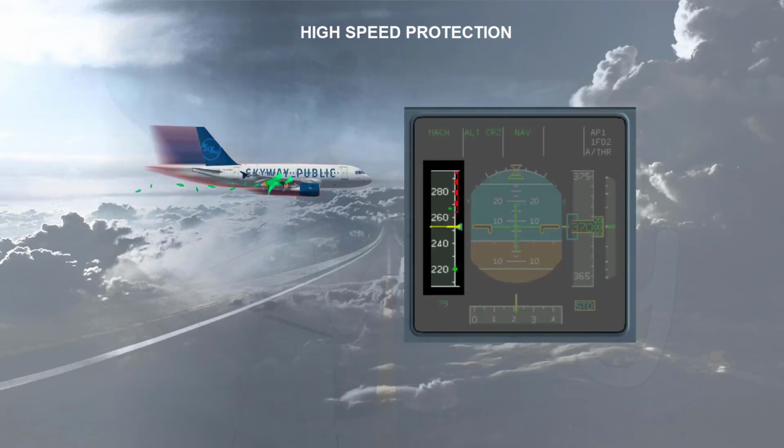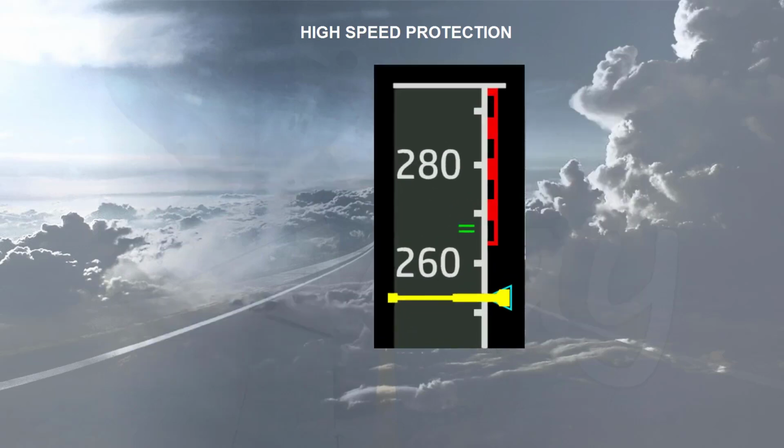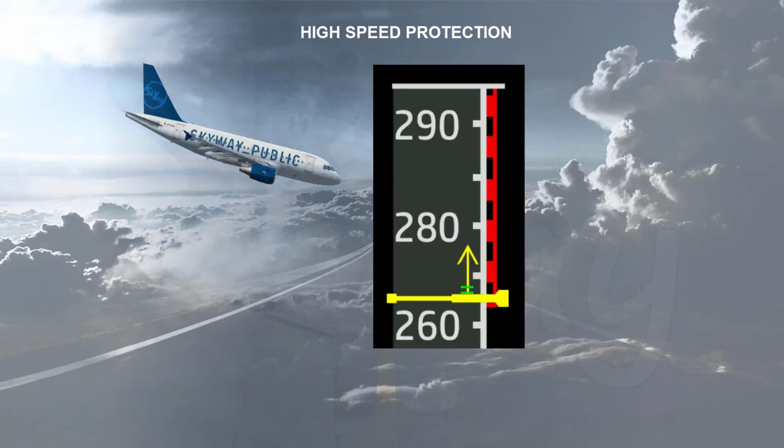The protection we will look at now is the high-speed protection. It is designed to prevent the aircraft from exceeding maximum speed. These protection limits are displayed on the PFD speed scale. VMO-MMO is shown as the bottom of the red and black barber pole. Green dashes indicate the speed at which the protection is activated. When the airspeed or Mach increases above VMO-MMO, an overspeed ECAM warning is triggered, as shown in the autoflight chapter.